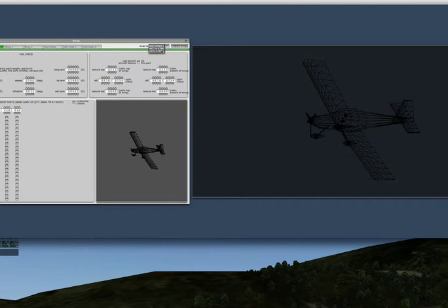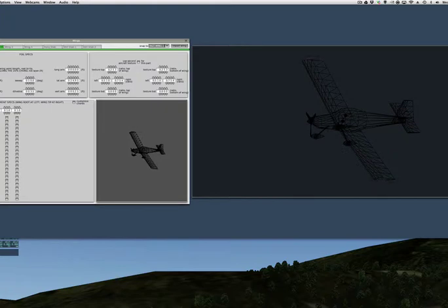Yeah, right stab, vertical stab, snap to. You could also do an import wing, but that's a little beyond the range of this class. It doesn't preclude you from doing it. All right. Okay, folks. Any questions about how you would do this now, as far as Plane Maker changing the wing length, and therefore changing aspect ratio of the airplane?